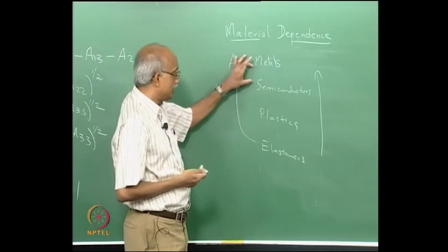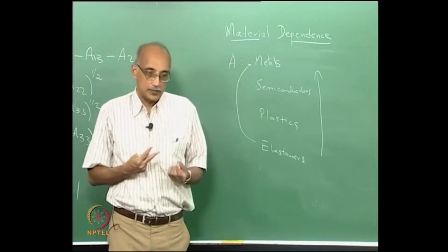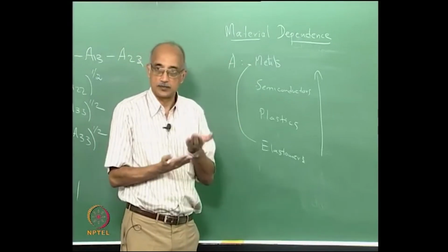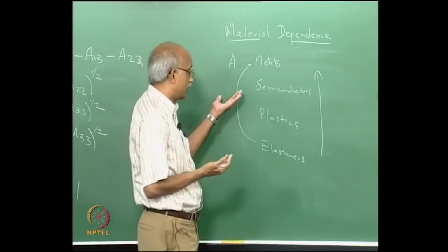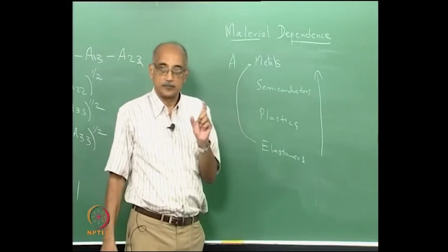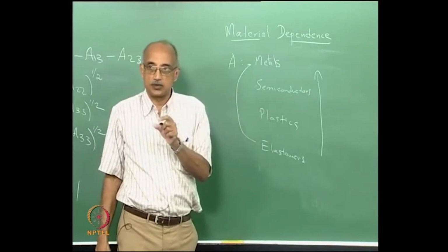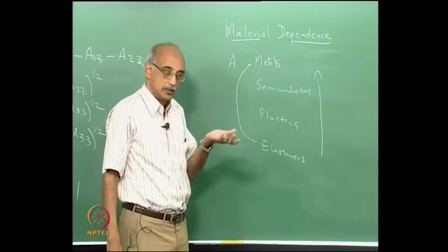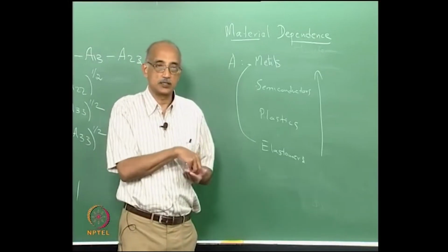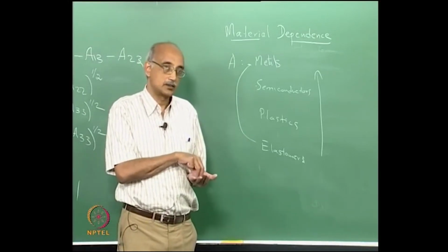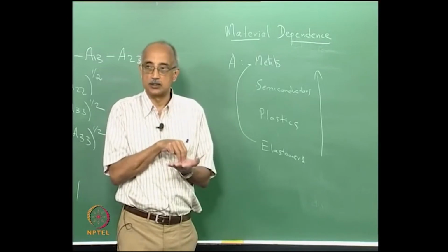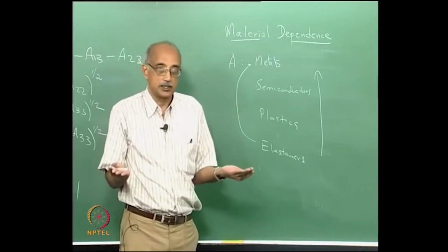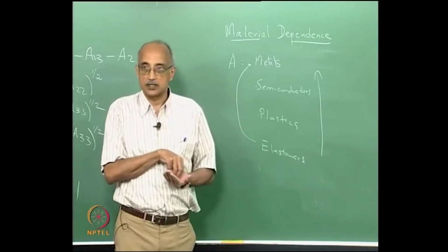Also, you know, the combinations are interesting. When you have, for example, a silicon oxide particle approaching, let us say, a silicon surface, the Hamaker constant for silicon is greater than the Hamaker constant for silicon oxide. So what does that imply? The affinity of silicon for the silicon oxide that is approaching is greater than the affinity of the silicon oxide for the silicon. Now again, that is mostly positive, because that means that if you are trying to make silicon, silicon oxide is not going to act as a contaminant.